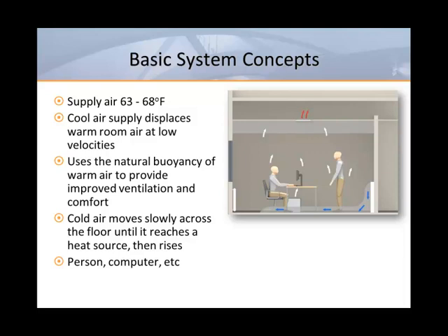In office applications, the heat sources in the occupied zone are usually people and equipment. When the slow-moving pool of air encounters a heat load, it quickly rises and carries the heat and pollutants towards the ceiling. Internal heat loads and contaminants are then carried away by the return air. We refer to this as a thermal plume.